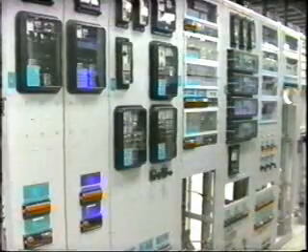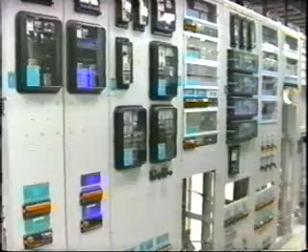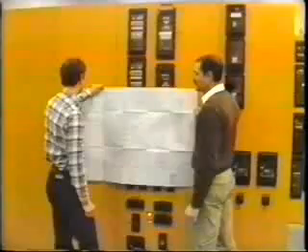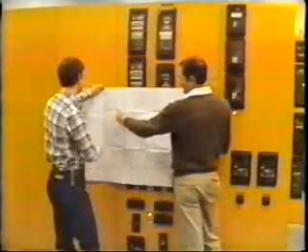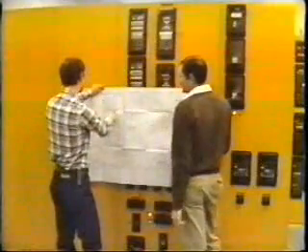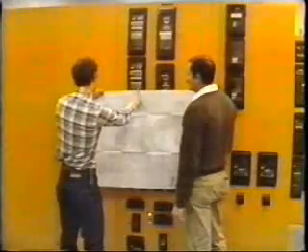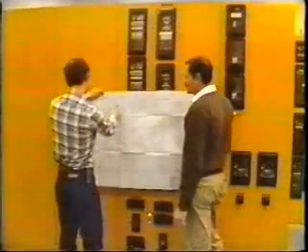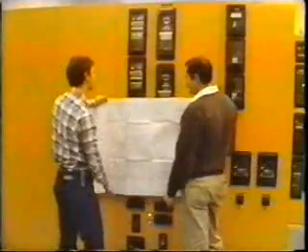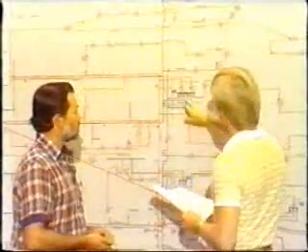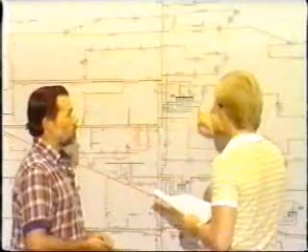Even if the protective relays, breakers, CTs, VTs, and communication equipment all seem to work exactly as planned, our job is not complete. We still need to investigate each disturbance after the fact. But why is it necessary to go back and analyze faults after they happen? Well, this is done for two basic reasons. First, to check that the relays and breakers are operating as intended, and second, to explain any misoperations and predict any future problems.